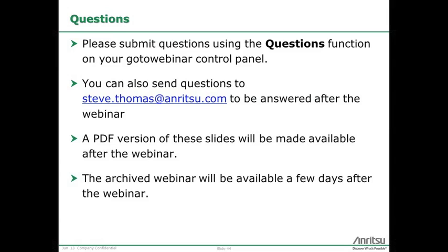Yes, that's an interesting question. There's a lot of confusion about MIMO. It really is using multiple transmit antennas and possibly multiple receive antennas. And the simple answer is it has no effect at all, because in general the transmit and receive antennas are both very close to each other, and the effect of the interference on both of them is essentially identical. So, for example, if you have a situation with one transmit and two receives, you might want to pick the test port on the one receive to make sure there's no leakage from the downlink signal. But other than that, there's nothing to worry about.